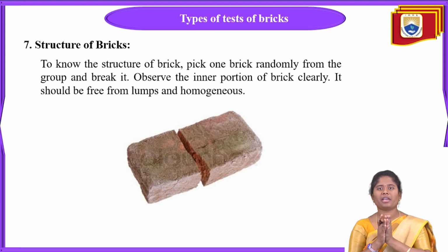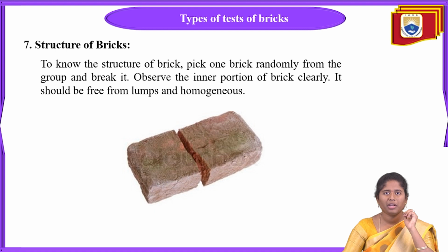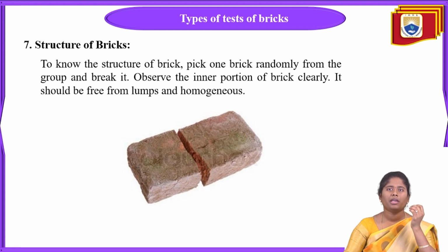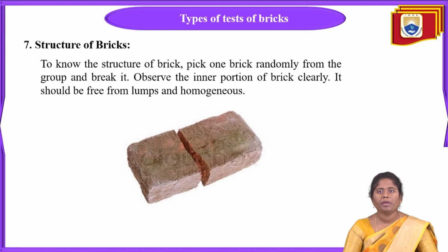Means after breaking it, we are going to see the inner portion of that brick, and that inner portion should be free from lumps, and it also should be homogeneous. After seeing the inside part, it should be free from lumps, and it also should be homogeneous throughout its structure. That is nothing but the structure of the bricks.